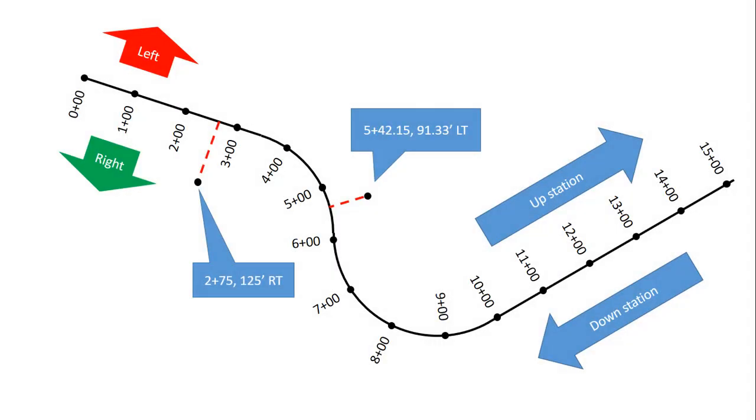In this video we're going to examine stationing. Stationing serves as the backbone to all engineering projects. It gives you a reference to all points that need to be staked, so any improvements are going to be referenced to this baseline, to this center line, and they're going to be referenced as a station and offset from that baseline. So you can see we start here.